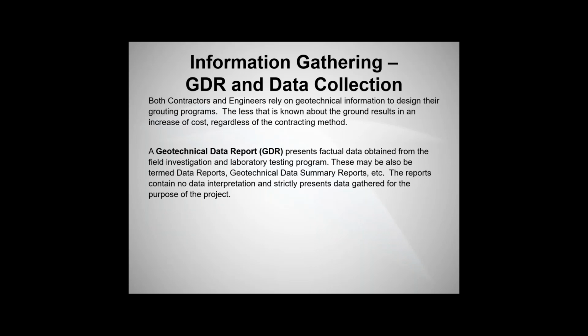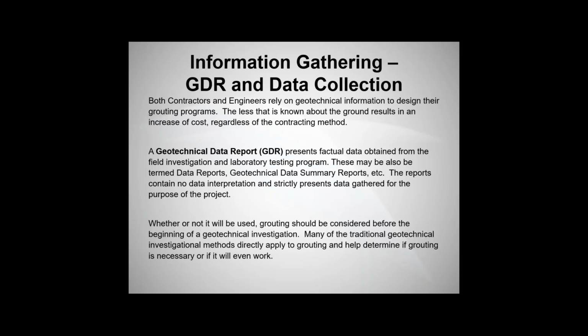Typically, for these investigations, either a geotechnical data report or a geotechnical data summary report is used to present the factual data about the ground. This is strictly the test results, the laboratory results, the boring logs, stereo plots, things of that nature. The bottom line is that there is no interpretation associated with these reports. But as we're collecting all this information in the beginning phases of design for your project, you need to be thinking about grouting and whether or not it's going to be used. It should be considered.